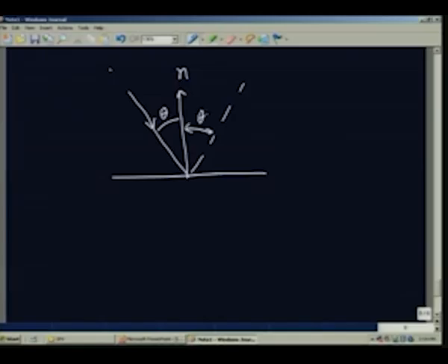So, let us just see what will happen. If I draw that surface, I have got radiation coming in this direction. This is a normal to the surface. So, this is the angle theta at which it is falling on it. Now, what will happen if I draw a line corresponding to the specular direction, this is also equal to theta. So, there will be more reflection along this direction and less along the other direction, therefore, you may get reflection like this.